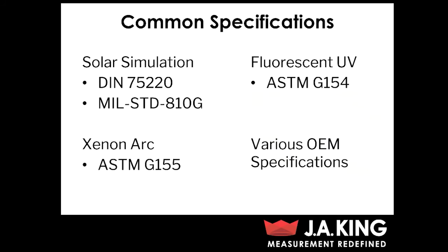And then MIL standard 810G, for those of you that aren't familiar with this test standard, it covers a lot of different types of testing other than just solar. But for most of the tests in this MIL standard, including solar testing, it provides really more of guidelines for testing, but you're going to have to tailor the test a bit based on the needs of your parts.